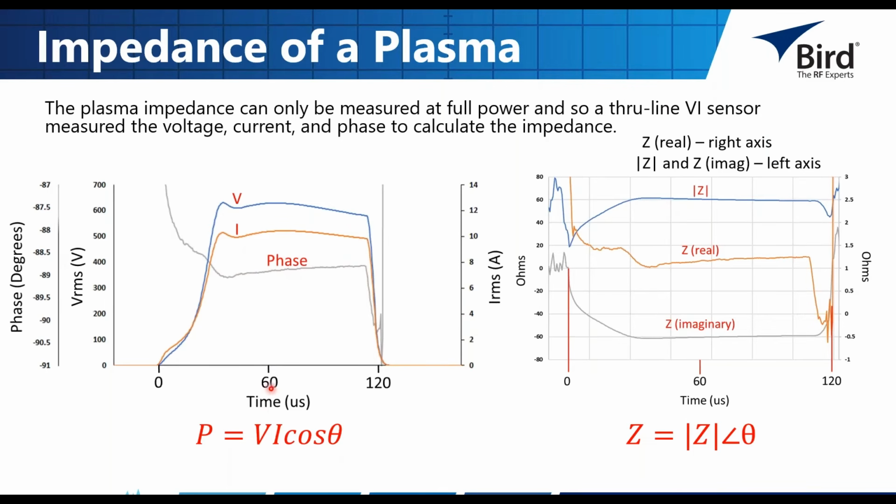And with that value, like we were looking at before when we were talking impedance, we can observe the magnitude of the impedance, and we have the phase angle here. We've got the real portion and the imaginary portion. So the matching network ended up getting us fairly close to approximately 60 ohms of impedance magnitude, so it got us pretty close to a good impedance match.